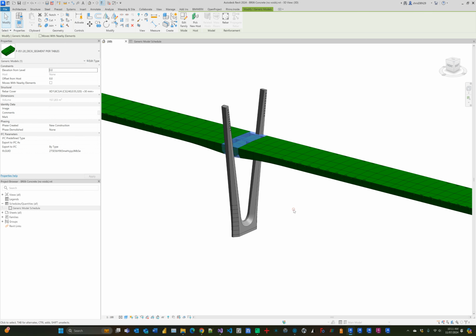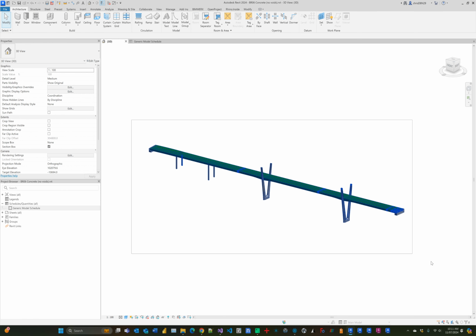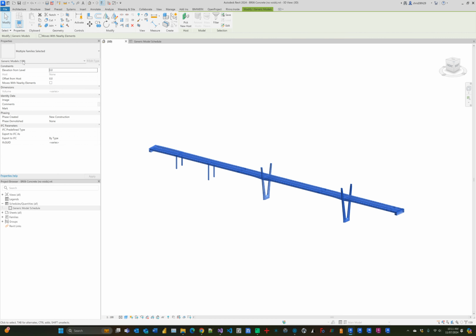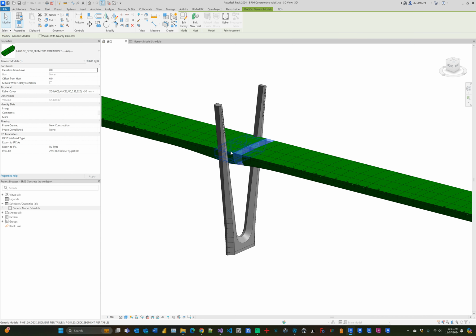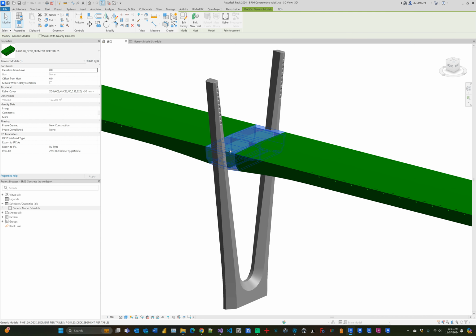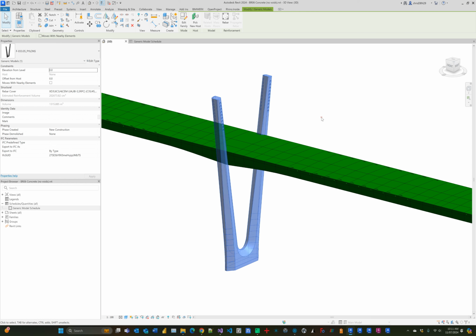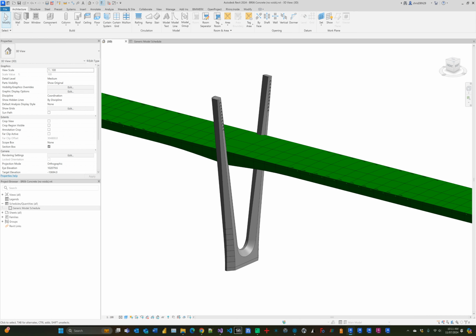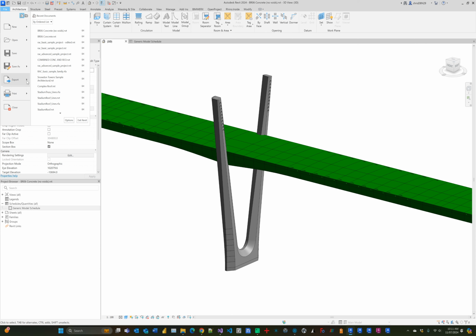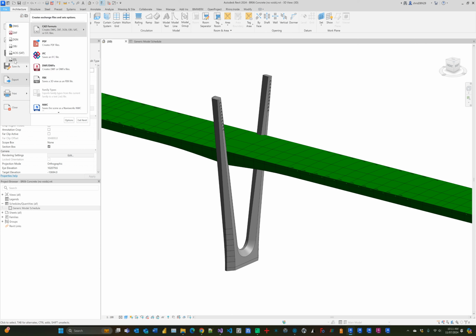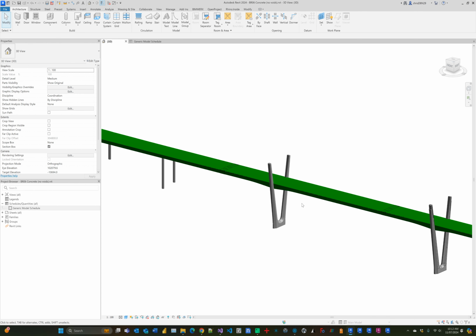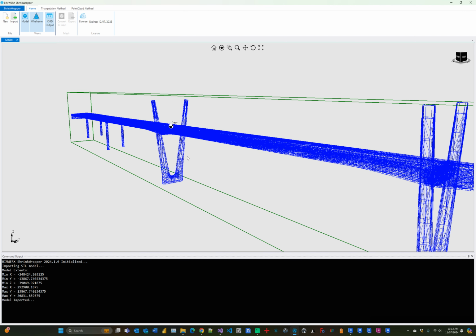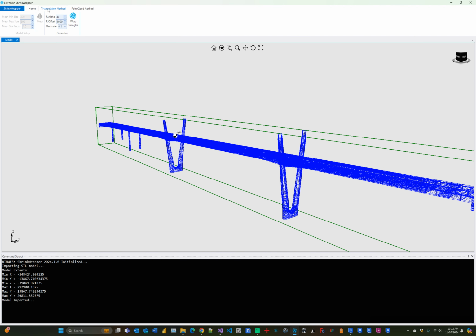So, we try and strip out the elements in Revit in the view by hiding stuff that we don't need to see. But in terms of creating a wrapped geometry, a solid volume of the exterior of this model, you can imagine if we had to manually do that, we'd have to create a profile around each of those deck segments and then extrude them across. So by exporting this to STL using ASCII format and setting the resolution to coarse, we can speed up this process using ShrinkWrapper. So this is what it looks like when we import it.